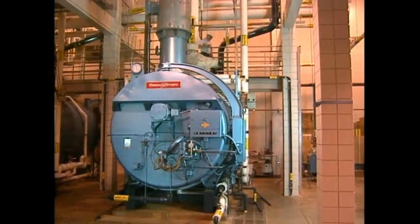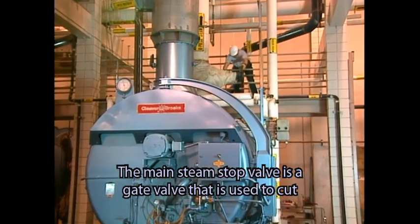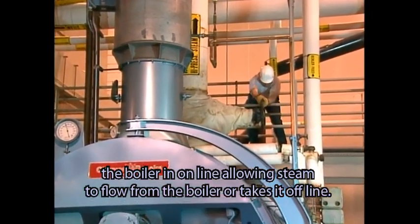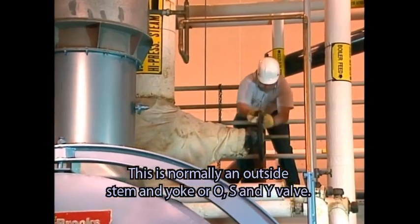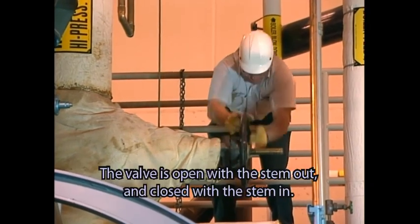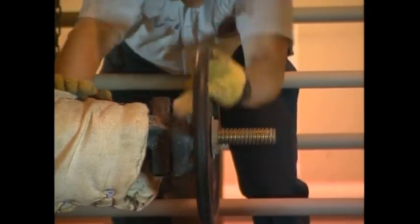Steam valves. Steam valves commonly used include a gate valve and a globe valve. The main steam stop valve is a gate valve that is used to cut the boiler in on line, allowing steam to flow from the boiler, or takes it offline. This is normally an outside stem and yoke, or OS&Y valve. The position of the stem indicates whether the valve is open or closed. The valve is open with the stem out and closed with the stem in. This provides quick information to the boiler operator.